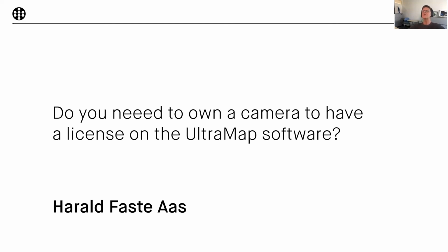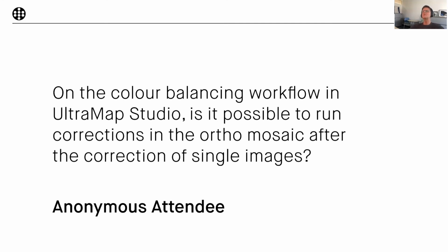Next question is, on the color balancing workflow in UltraMap Studio, is it possible to run corrections in the ortho mosaic after the correction of single images? Bernhard, would love to hand this question over to you. Yeah, so in the color balancing workflow, we follow this approach that first there is the automated adjustment of the full image block.